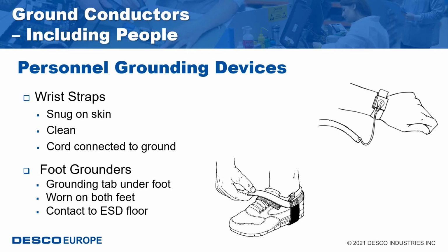Grounding is very important for the removal of static charges that are generated on conductors. Human beings are conductors and major generators of static electricity. Therefore, we must remove electrostatic charges from any person who will come in contact with ESD sensitive components or assemblies. Removing static charges from the human body is best accomplished by grounding personnel by means of personnel grounding devices such as wrist straps or ESD footwear.